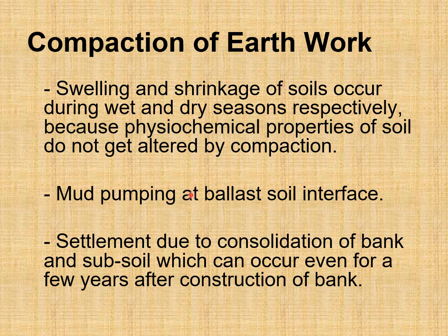Mud pumping, you can take it like this: if there is soil and the moisture content is very high, and above the formation the ballast is present, and when load is transferred through the ballast to the very soft formation, then there is a chance of mud coming in the upward direction, and that is called mud pumping. Settlement due to consolidation of bank and subsoil, which can occur even for a few years after construction of bank.